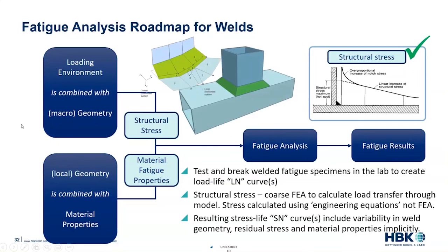So this is where we have a simpler finite element analysis model, which is not modeling each weld in detail. In this example, we've got one shell element for the weld itself.